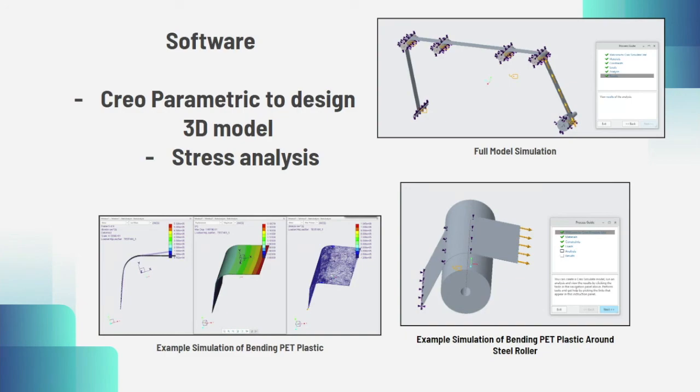The major difference from the initial calculations is the existence of the rollers that created more friction than originally anticipated. This means that the tension added by the rollers was accounted for in the tension calculations. Therefore, the torque applied to the roll was reduced so that the increase in tension does not permanently deform the plastic substrate.